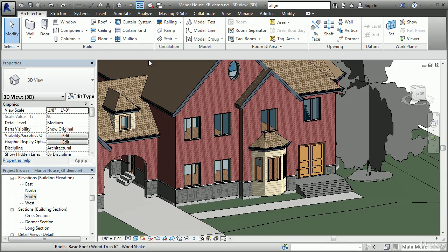Revit uses parametric objects and parametric relationships to help accommodate the inevitable changes that need to be executed when developing a model. A parametric object is an intelligent object that can have various sizes, materials, or other parameters assigned to it. These parameters can be accessed and modified through a dialog box, allowing you to quickly and easily create variations on a single object. A desk could have parameters such as length and width that could easily be modified without affecting the height of the object.